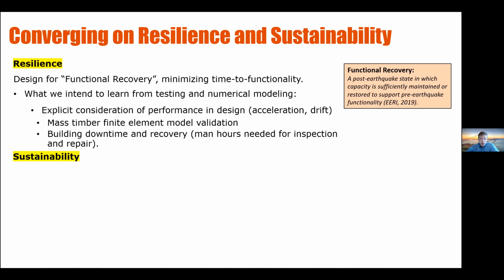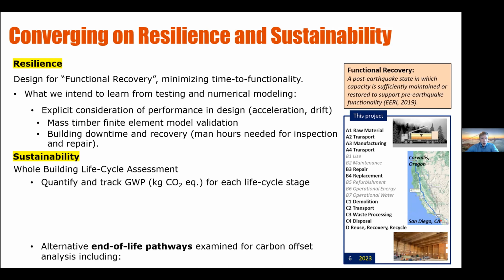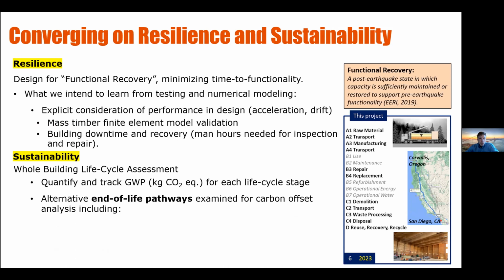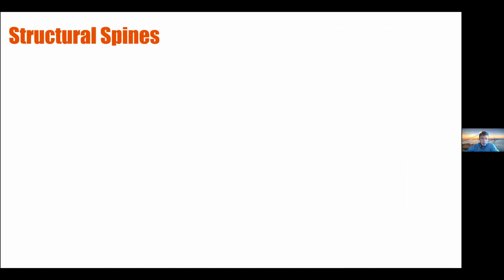To address sustainability goals within design, we are conducting a whole building life cycle assessment to quantify and track global warming potential at each life cycle stage, while also examining the carbon offset associated with alternative end-of-life pathways, including reuse, incineration, and landfill.